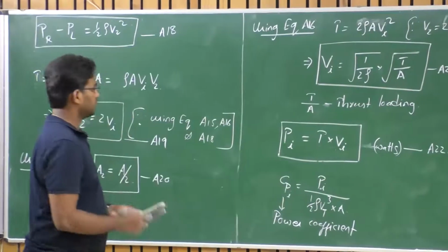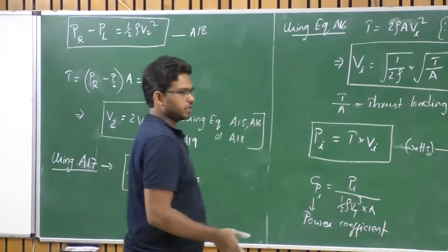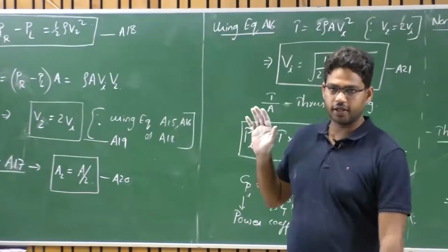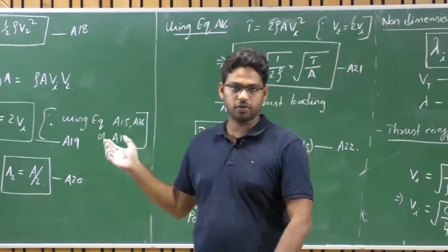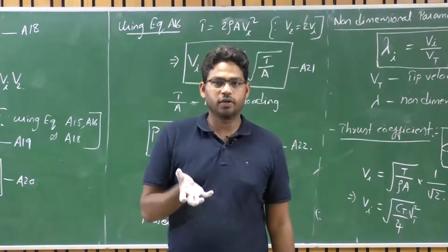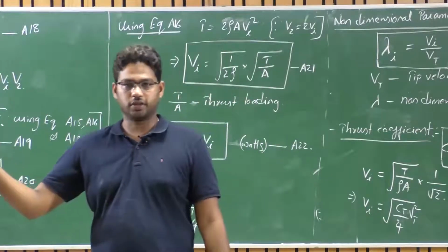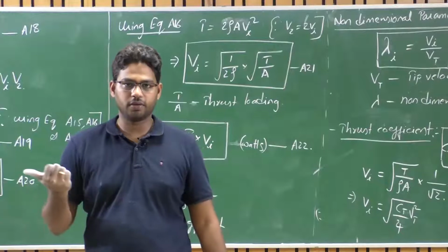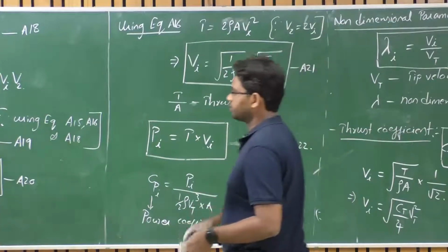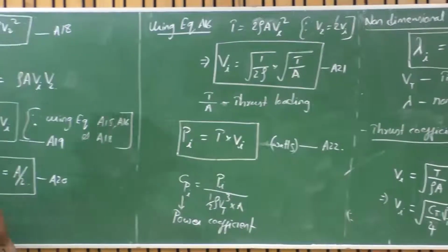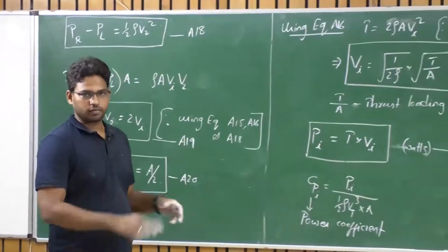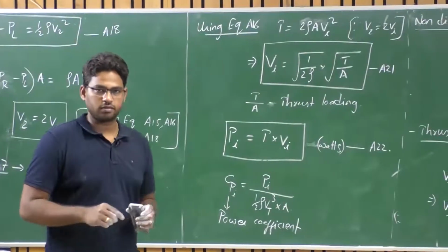So what we can observe here is that the pressure difference across a disk creates a force called thrust in the forward direction. If that forward direction is the direction of our motion, and you fix that setup rigidly to our aircraft, then the aircraft will also experience thrust T in that direction, right? Later on we'll come back to that point. We'll solve an example about this momentum theory, and then get back to how thrust is going to help us.